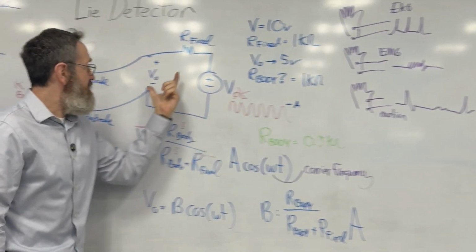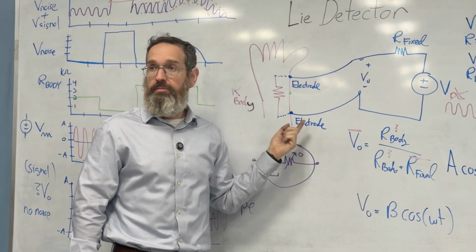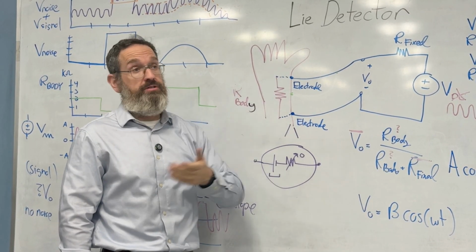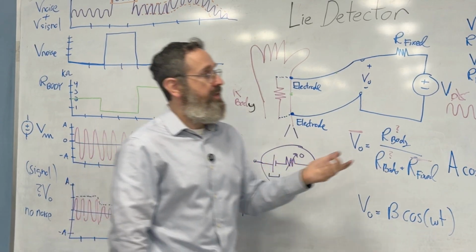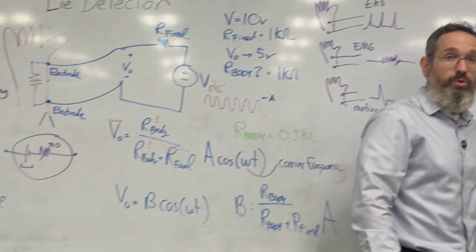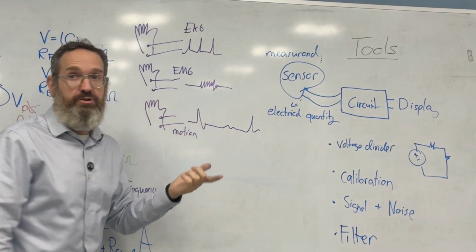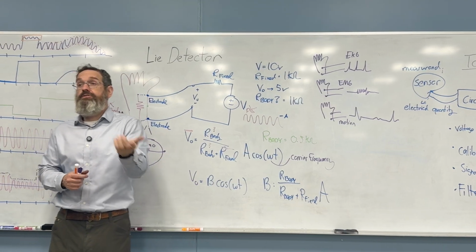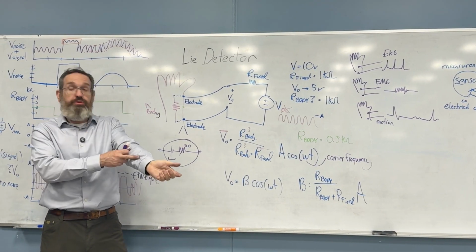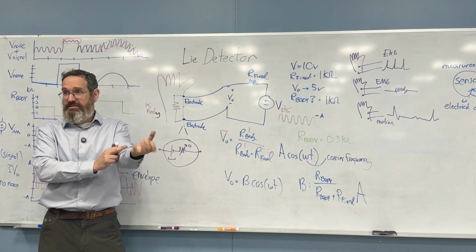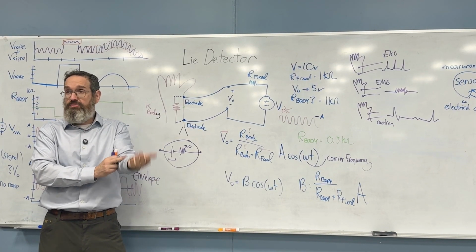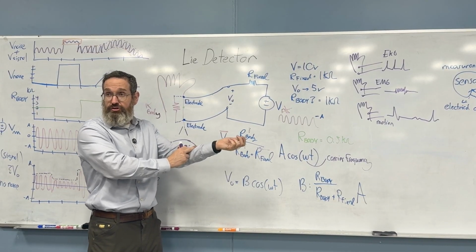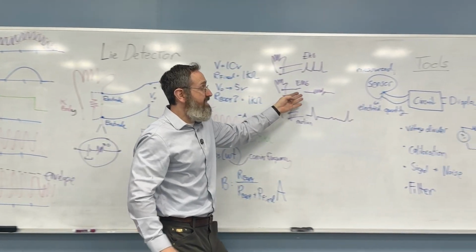And so by putting these electrodes on your sister's arm, why wouldn't you see an EKG? Well, because I don't want to see it? No. It's now not your signal, it's now your noise. Since this is exactly how you would make an EMG sensor, if I said measure the muscle activity in your sister's arm, you would put the 2 things here. You'd connect your device and you would see it very nicely, right? So now every time she moves her arm, every time she moves her fingers a little bit, it's going to contract muscles in the forearm. So you would see that as well.